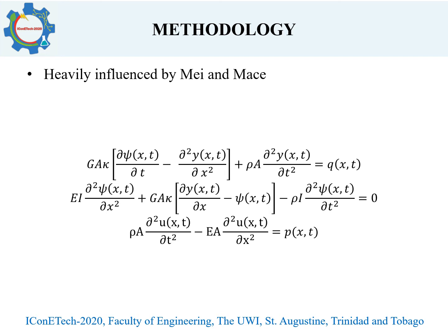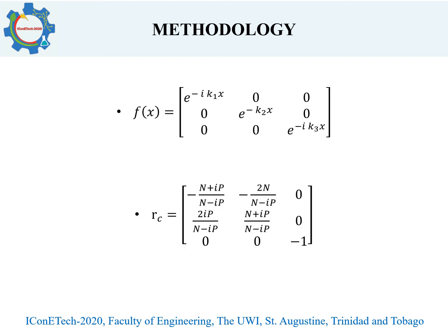Below are the equations of motion for the in-plane vibration of a Timoshenko beam. The fundamental equations are manipulated in various ways to obtain the transformation matrices, which are outlined in the paper. But I would like to highlight two specific matrices used in the L-beam structure, f of x, which is the propagation matrix, and RC, which is the boundary condition for a clamped edge.